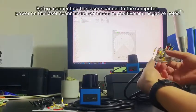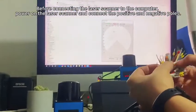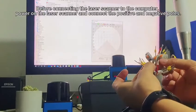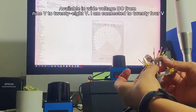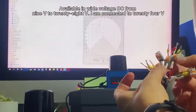Before connecting the laser scanner to the computer, power on the laser scanner and connect the positive and negative poles. Available in wide voltage DC from 9V to 28V. I am connected to 24V.